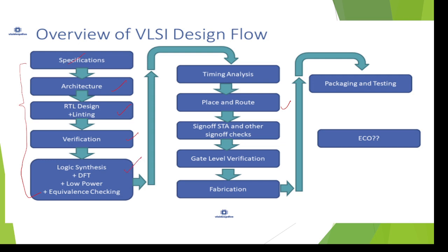If it executes properly without any errors, you can go for the backend process. Here it is timing analysis, to check whether we can meet our required timing constraints or not. Only then do we go for physical design, and in the backend process there are placement and routing, as well as floor plan, which is very important.